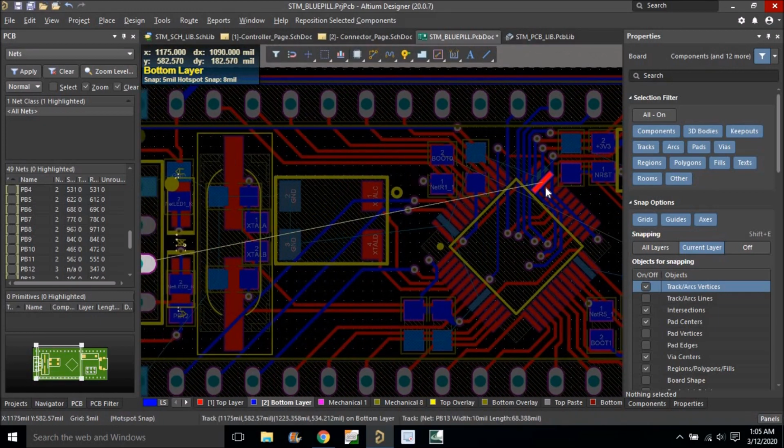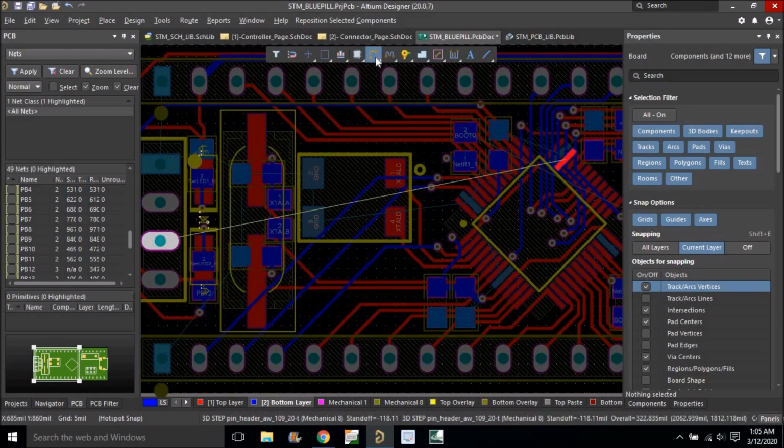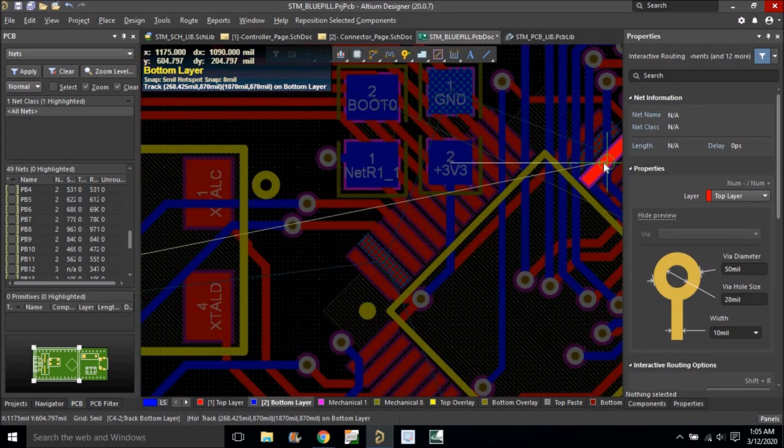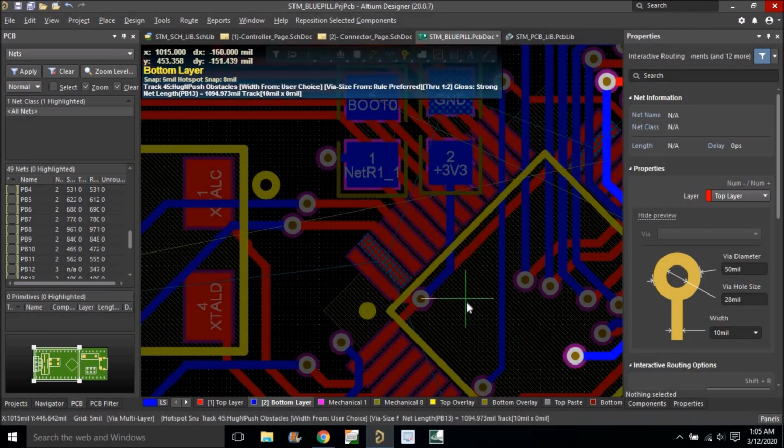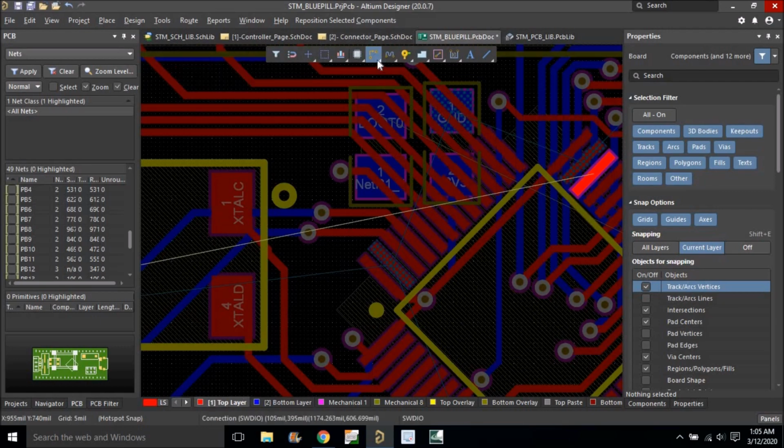Now we'll connect this thing also, so it's going this side. How will we make it connect? So this will be here, from here it will be bottom to here. Okay, fine. We'll just drag this connection here. Hold on, select the top layer first.